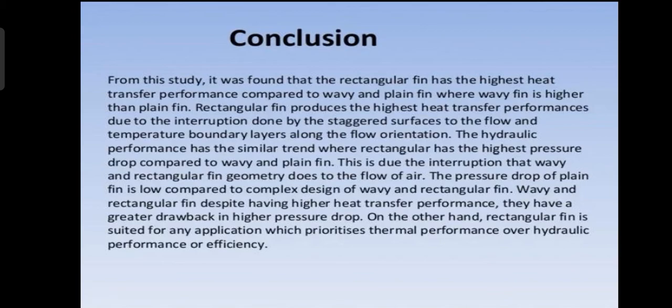The hydraulic performance has a similar trend, where rectangular has the highest pressure drop compared to the wavy and plane fin. This is due to the interruption that the wavy and rectangular fin geometry does to the flow of air. The pressure drop of plane fin is low compared to the complex design of wavy and rectangular fin.